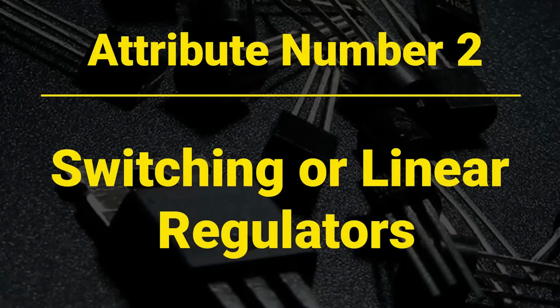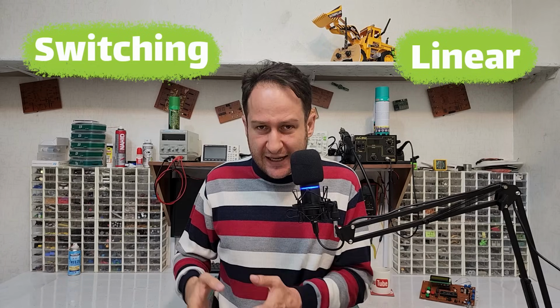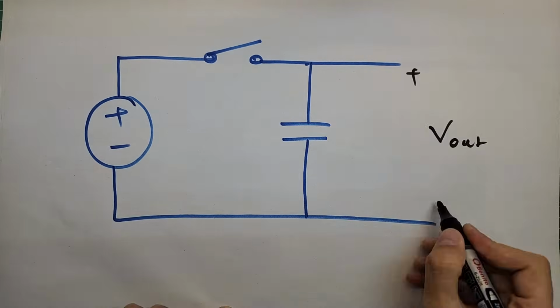Attribute number 2, switching or linear regulators. Any voltage regulator will fall into one of these two categories, switching or linear. This attribute indicates the mechanism of operation that the regulator employs to keep the output voltage constantly equal to the desired voltage.